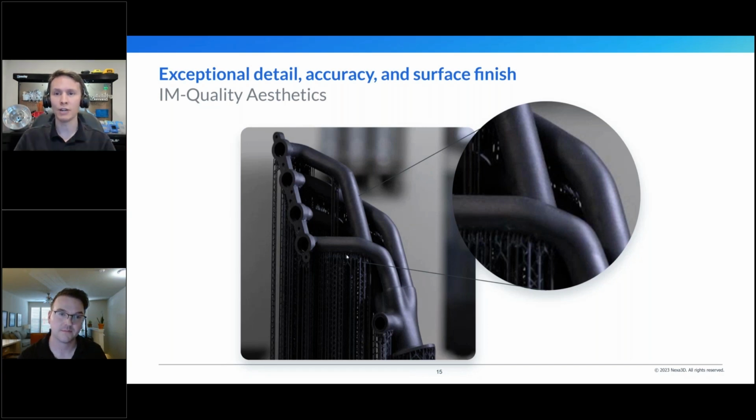If you're not familiar with resin-based processes, all resin-based processes, most 3D printing does have support structure that's made of the same material that you're producing the part out of, with some exceptions in soluble support for FDM or SLS or MJF, which don't require it. Those are removed afterwards and lightly sanded or cleaned off of any residual nubs, but it's there to hold it in place because gravity exists, and then afterwards we remove those.